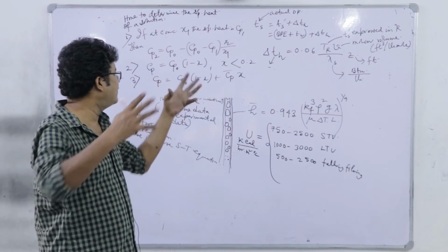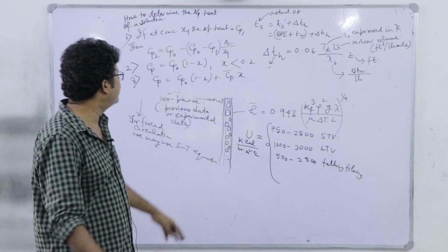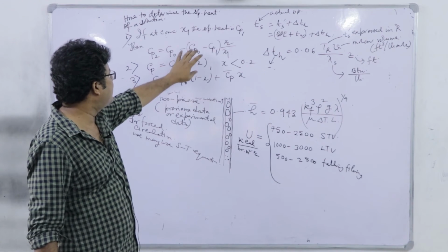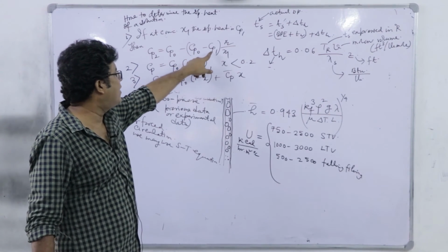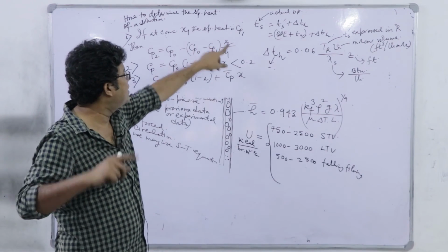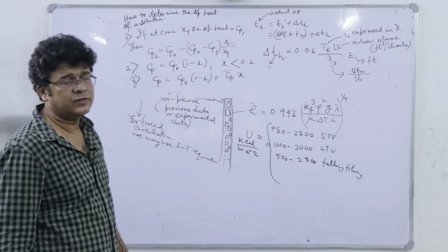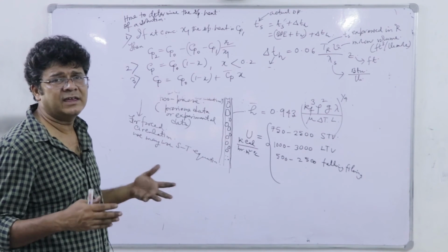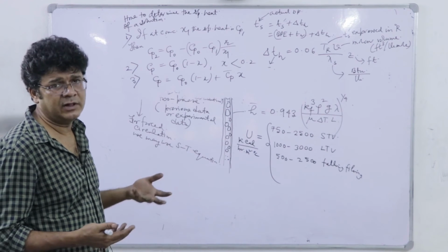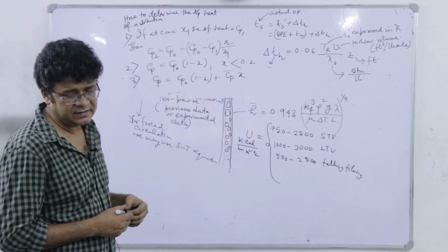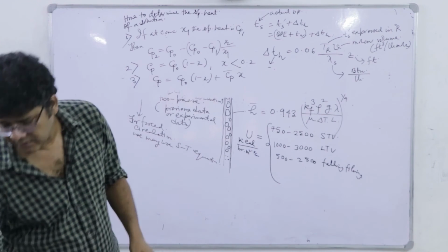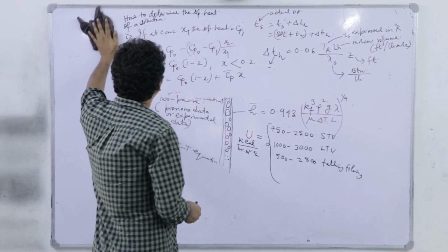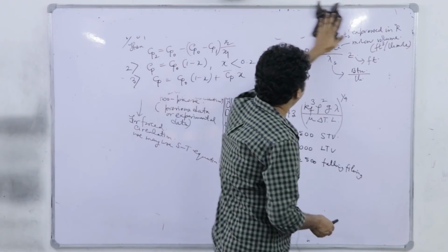This is a kind of linear combination, right. Most commonly we generally use this, where we have to know at least one specific heat for a specific concentration or mass fraction. Additionally we have more accurate Cp versus x tables or plots available in design books like Ludwig or Kern. So that is about the specific heat.